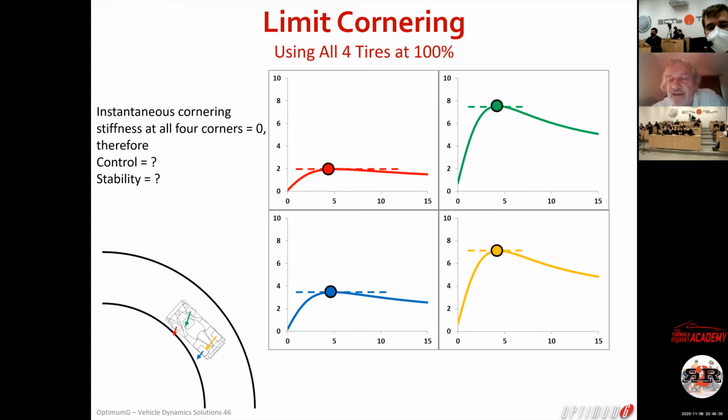a good and a bad car. This car is good for 2 reasons. You are using lateral grip versus slip angle. You use each of the tires, left front, left rear, right rear, at the peak slip angle. Fantastic. You did a fantastic job as a race car engineer and a driver and so on, okay?